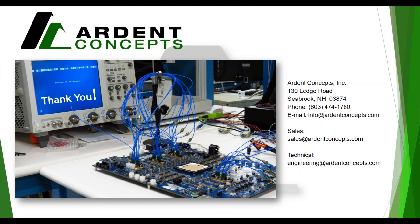All right, great, thank you. So another question we had here is they ask, with the compression mount, how do I keep my PCB from bending? Yeah, so we supply with all our terminators a stiffener block. The stiffener block is recommended for printed circuit boards that are less than 1/16 of an inch thick, so 63 mils. The stiffener block is immediately exchangeable with PEM nuts.